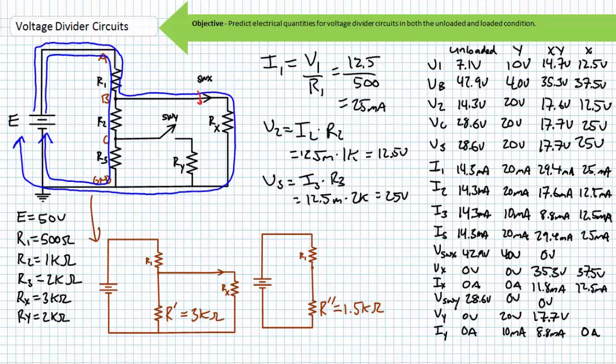No current will flow through open switch Y, and no voltage will be dropped across load resistor RY. Given node C is 25 volts higher than ground, open switch Y will experience a 25 volt drop across its two terminals. Ideal closed switch X should exhibit no voltage drop across its two terminals. Again, this circuit analysis yields radically different values than any of our previous analyses because this is a radically different circuit than our previous renditions and must be approached as such.